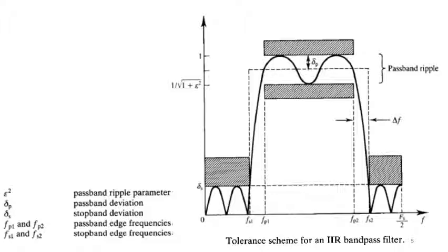We discussed this type of figure in the previous lectures while we were doing the FIR system. For frequency selective filters, whether they are high pass, low pass, or band pass, the frequency response specifications are often in the form of a tolerance scheme, as shown here. Here we have a new parameter, which we call the pass band ripple parameter. The pass band ripple is basically the difference between the minimum and the maximum deviation in the pass band.